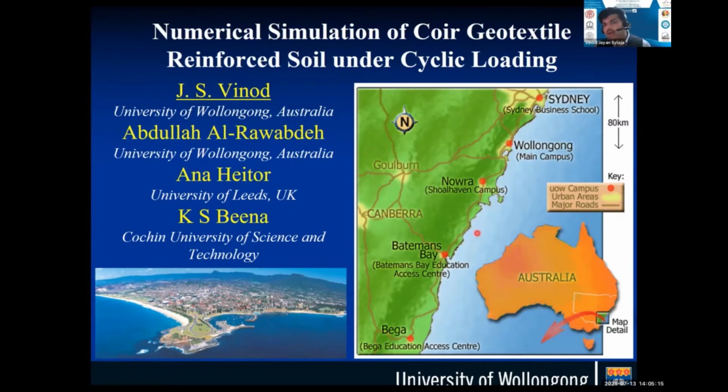When we were investigating the literature in this phase, we were able to find a lot of work on monotonic loading of these materials and carefully looking at the interaction mechanism of soil and coir geotextiles, but we couldn't find much detail on this material's performance under cyclic loading conditions, especially under a heavy, fast-moving truck or high-speed rails,